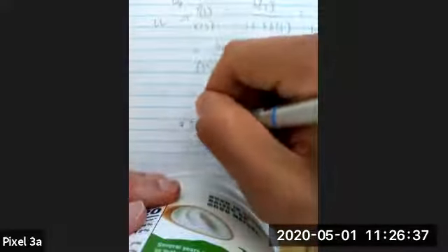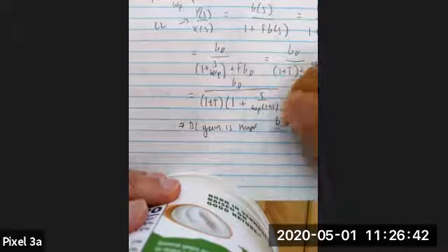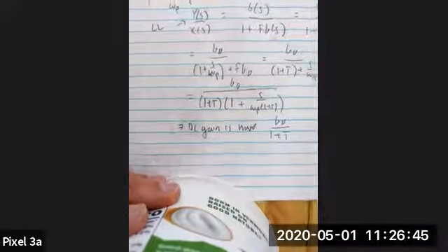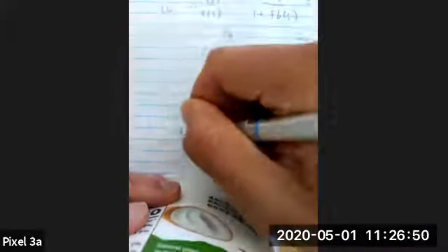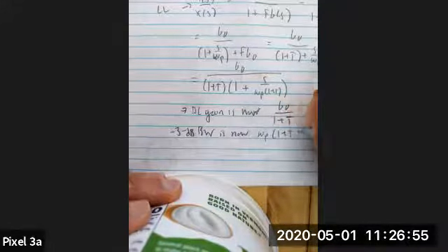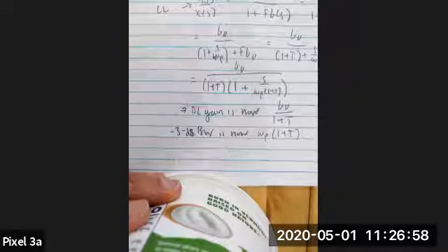And so now we can make qualitative determinations about the DC gain of the closed loop system as well as the bandwidth of the system. So what we see in this case is that the DC gain is now g naught over 1 plus T, and the bandwidth, the minus 3 dB bandwidth, is now going to be omega p times 1 plus T. Any questions about that?